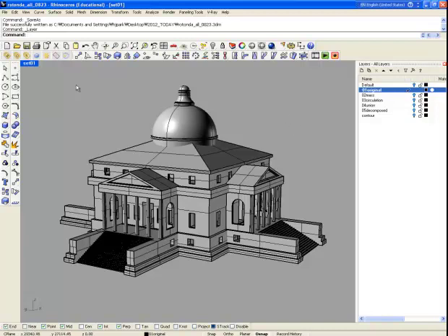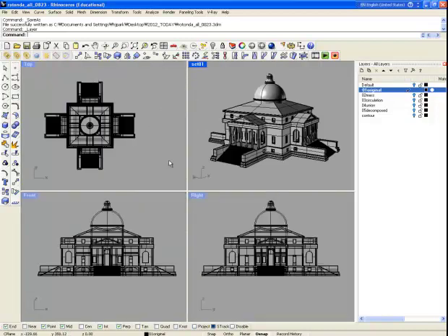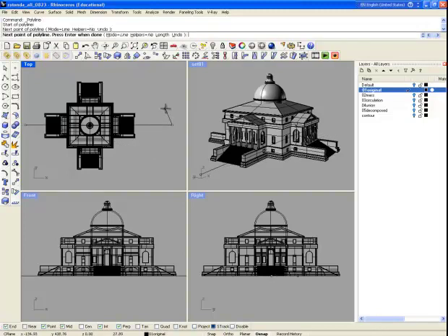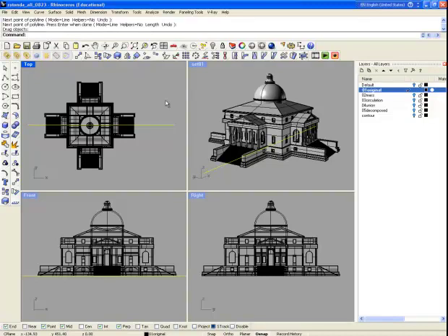So let's go back to the four different views by clicking this viewport. You may want a side section cut, or a plan section cut, or something else. For now, we are going to have a side section cut. So what we want to do is draw a section line. Click somewhere over there in the top viewport, then hold the Shift key, which gives you a straight line, and then spacebar, and then you can adjust which way you want to put this cutting line. After you set the cutting line, make sure that your cutting line goes through this 3D model, not in the model, right? Through it.